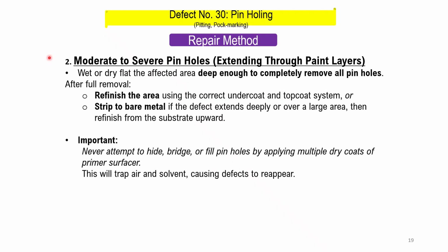In the second case, moderate to severe pinholes extending through paint layers, wet or dry flat the affected area deep enough to completely remove all pinholes.